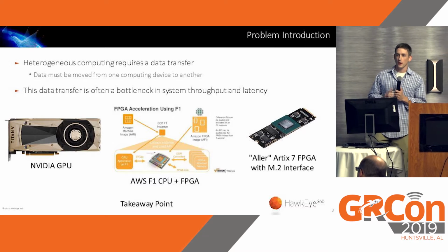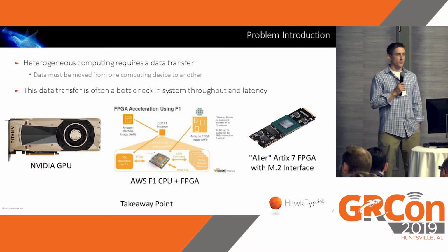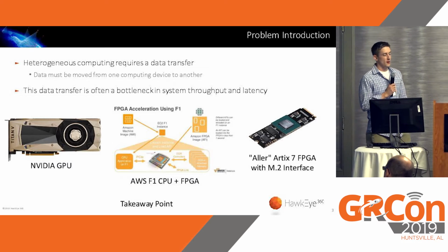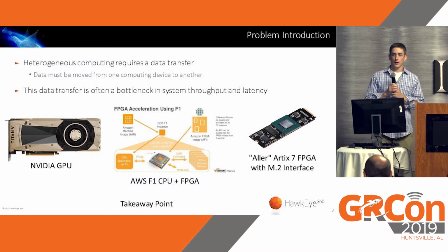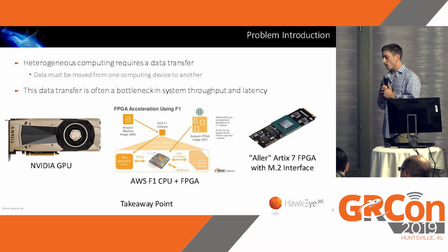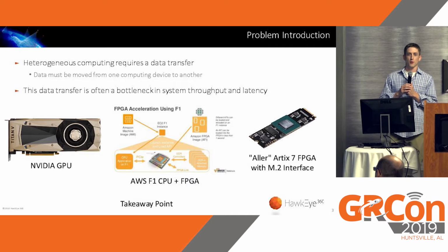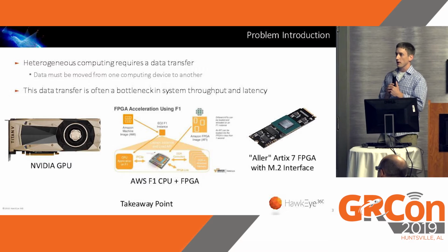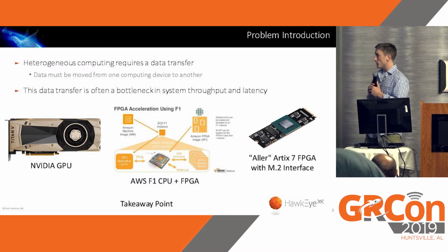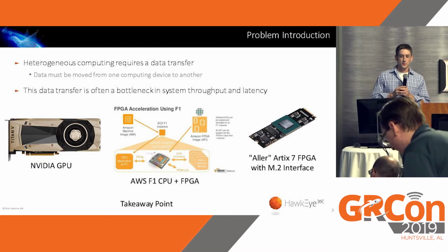All right, so we've got a low-power device. We can't do everything in the processor. Like I said, we have 5 watts of power available, and that's about enough for a Zynq system on chip, plus an AD9361. We don't have a big processor that we can use. We can't throw 50 to 100 watts and 8 cores at the problem and be happy with that. We have to be more efficient about the computing power that we have, and that means that we have to transfer data between the processor and some other computing architecture. In this case, an FPGA, but in many cases, this data transfer becomes a bottleneck.